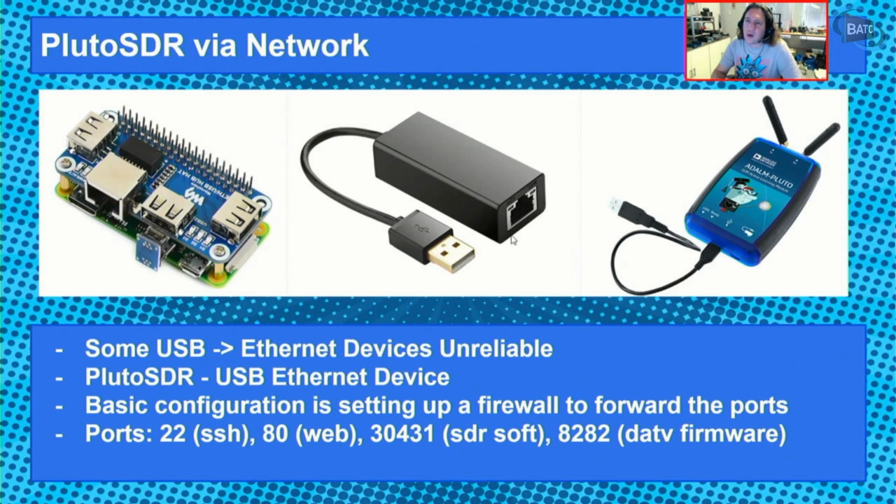They work fine for most things, your usual SDR console, narrowband, and even some DATV. But especially if you start doing some digital modes or playing with a high-speed modem, for example, it started giving me some issues on the throughput. And I found a note on the AMSAT-DL wiki regarding USB adapters that when using the high-speed modem specifically, they recommend a specific adapter.